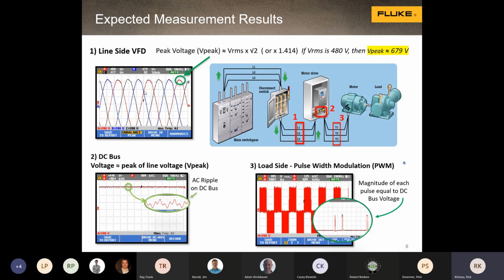But there's another important little detail here, and that is called the peak voltage on the voltage coming in. The peak voltage you can calculate for a sine wave, and these are sine waves. We'll talk about harmonics in a bit. If I tell you something is a sine wave, I'm telling you its shape is like this, and it has no harmonic distortion if it's a perfect sine wave.